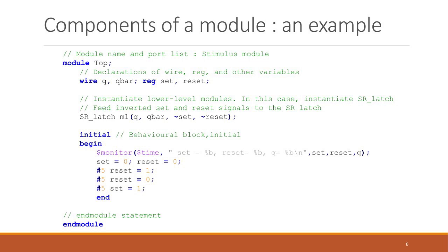So now we are done with instantiating the module to be tested. And now what we should do is give different inputs to this module we instantiated and observe the outputs. For this, we use an initial block we discussed in the previous lesson. And this type of behavioral initial block is a common component in a test bench module specifically.